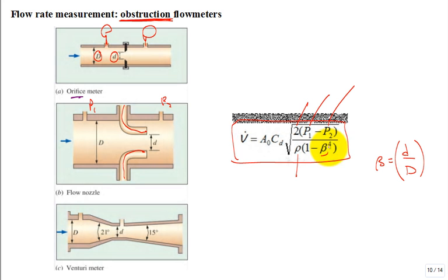But then you take it to the 4th power here. That would be like the ratio of areas squared. Then you have the nominal or smallest diameter giving you the nominal area, A naught, which would be pi d squared over 4. And then some discharge coefficient, which has to be experimentally measured. But once you have that, you sometimes curve fit it as a function of Reynolds number. You have a very accurate flow meter.